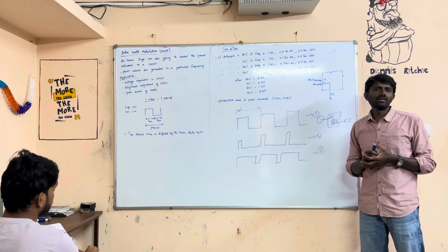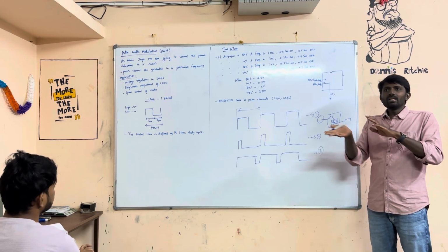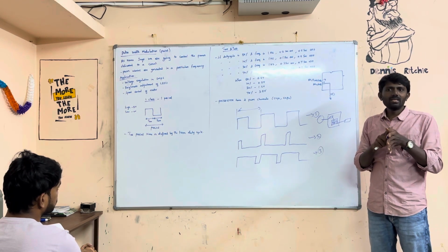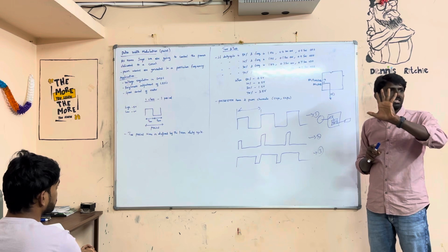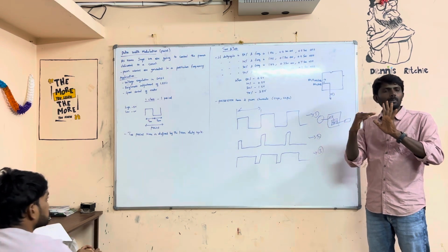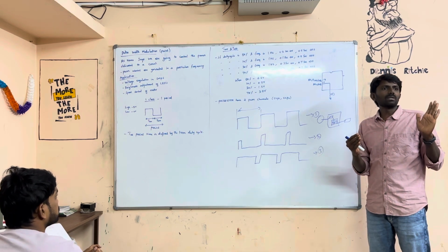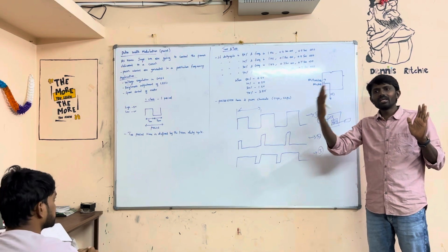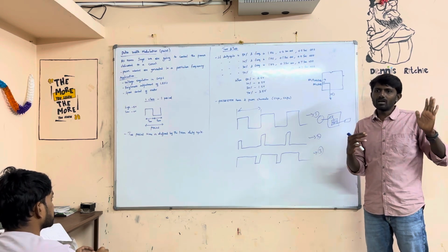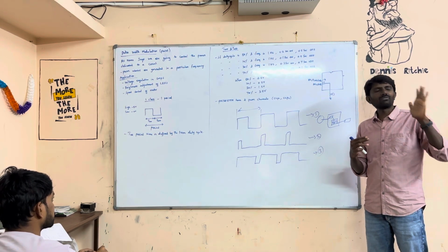Clear? Everybody getting right? So generally all our port A, port B, port C, port D, port E, these 5 ports are digital ports. Correct, right? Whether you are using it for input purpose or output purpose, input you give means either 0 volt or 5 volt. Output it is producing also, it will produce either 0 volt or 5 volt.